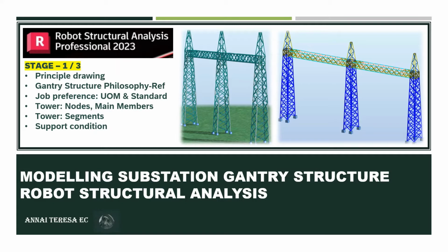Next, we are going to open the Robot Structural window, and in there we are going to do job preference, the fixing of unit of measurement, and the standards to be followed for material, loadings and design.